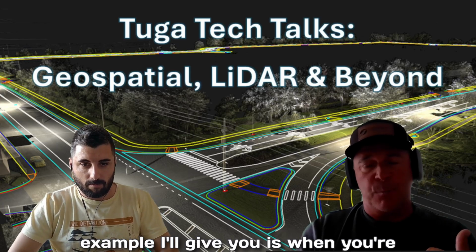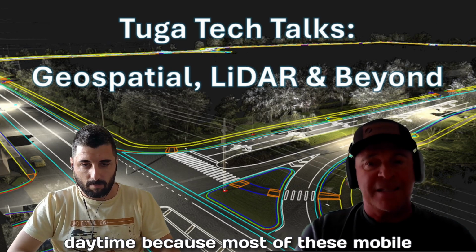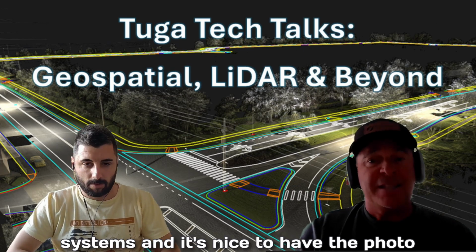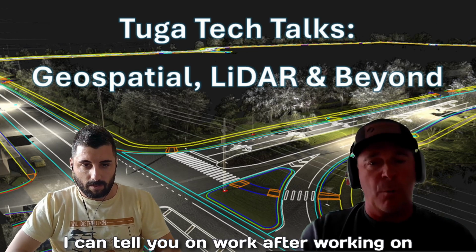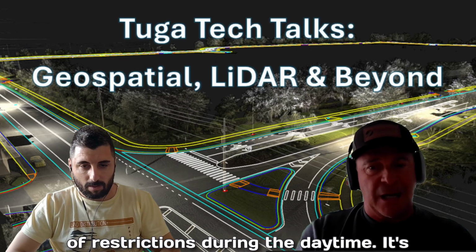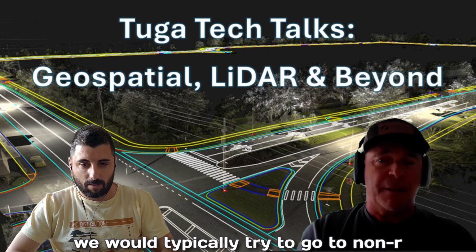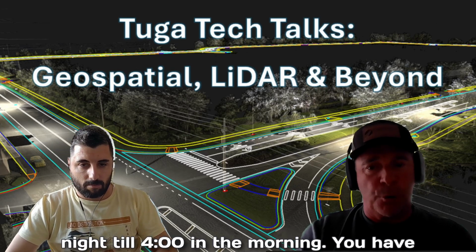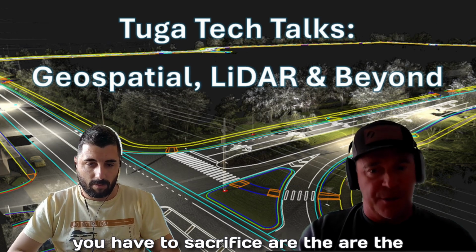Another example I'll give you is when you're collecting data on a railroad. Typically we love to work during the daytime because most of these mobile mapping systems have really good camera systems, and it's nice to have the photo as part of your geospatial data set. But after working on many railroads, I can tell you they have a lot of restrictions during the daytime. It's very difficult to be out there working on the railroad while they're operating. So we would typically try to go to non-revenue hours, which might be 11 o'clock at night till 4 in the morning. You have free rein on the railroad. The one thing you have to sacrifice is the images.